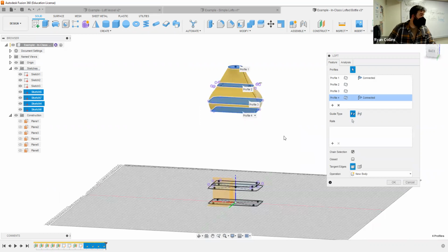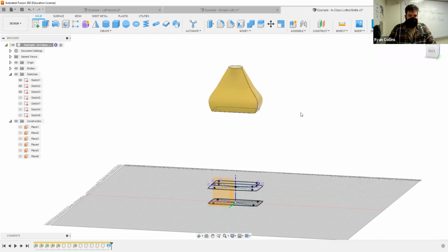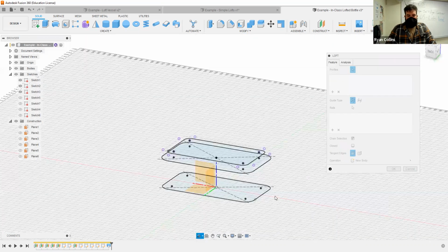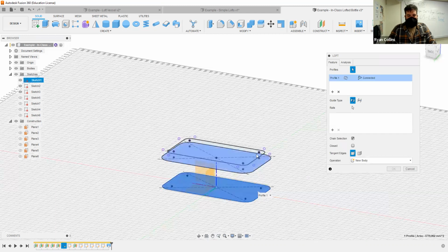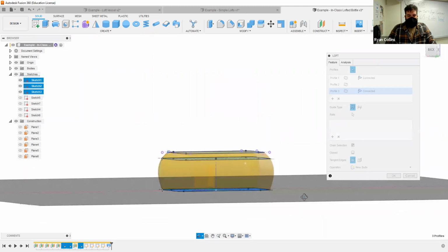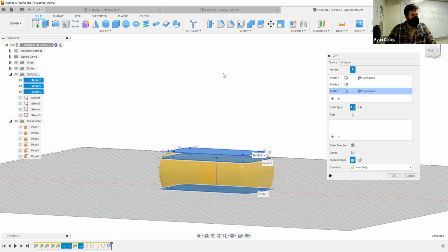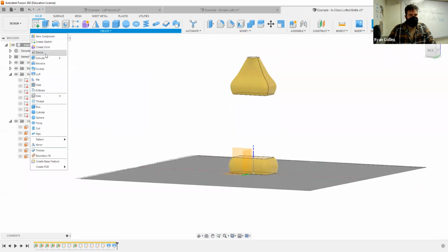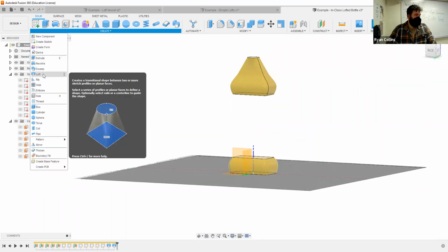So we're going to work with close enough with the dimensions on this project, because you're going to end up with a lot of stuff like this. So all right, I'm going to say that's one loft. Click OK. That made the top. Now let's do another loft, and I'll create the bottom, hopefully without the error. So starting at the bottom, moving up through the profiles. Okay. From there to there, from the next up, that's where it was giving me trouble. Okay. Now I have to make the middle. So create a loft, which in this case, between two of the same profiles is essentially an extrusion.